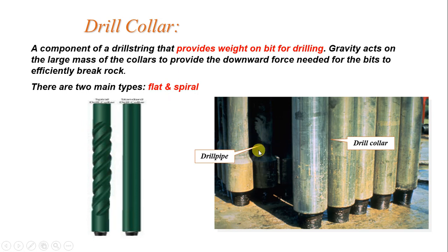As you see here, this is drill pipe, and you see the tool joint here is very short, and the drill collar doesn't have tool joint. So if you need to lay down or to make up the drill collar, you have to get a lifting sub for the drill collar. Okay, but for the drill pipe, you can just go with the elevator.